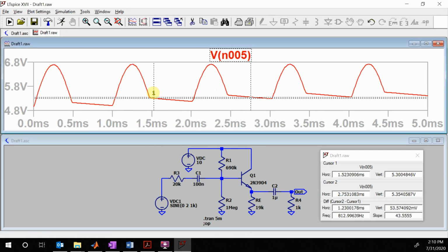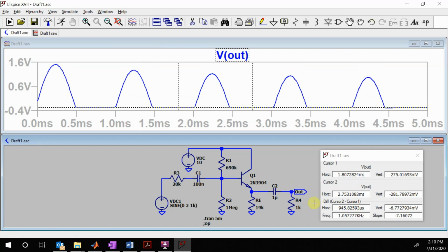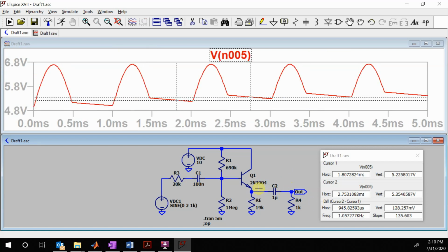And what is this? This is at about 5 volts, so 5.3 volts, it's clipping. So why in the heck is it clipping? Well, let's look at the voltage. Really we want to look over at this point rather than this one, because you can see that this one takes out the DC level. So let's go back to this side.